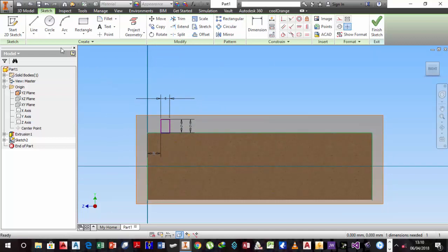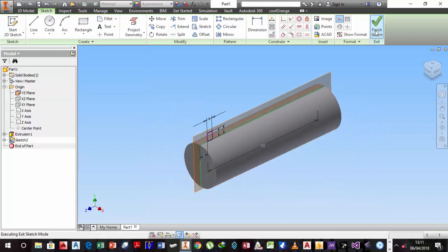Okay, the next part of it now is to get our rotation axis. You click on your line, don't click here, just track it downward until you get to this point. Now click and then move to your right, and your distance should be 88. Beautiful. Right click, okay. Now we want this line to be a construction line. Highlight it by clicking and move upward to format. Click on your construction line and it changes to construction. Okay, so click on finish.